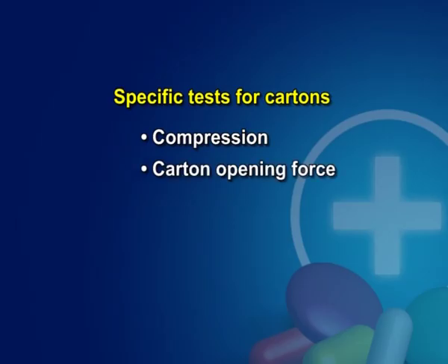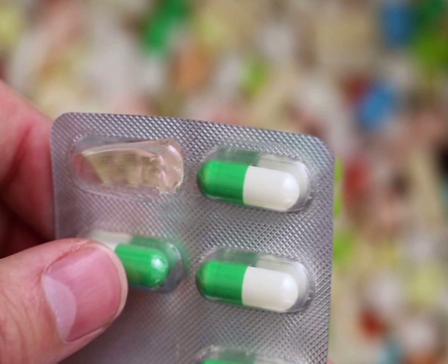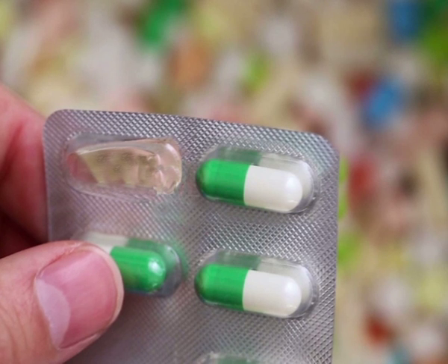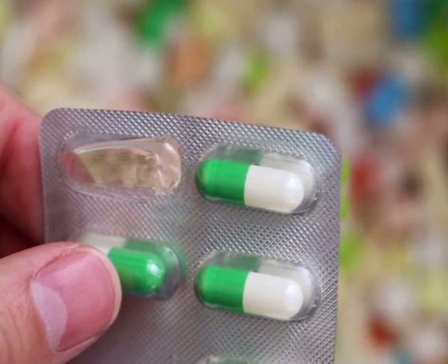Number 2. Carton opening force. The method that is often used is to hold the flat carton as delivered by its creases between thumb and the first finger and press. The carton should spring open into the square position without a need for unreasonable force. If the carton does not spring open or buckles in on itself, then it is reasonable to assume that those particular cartons will cause problems on any cartoning machine. This can be measured by instrumentation.